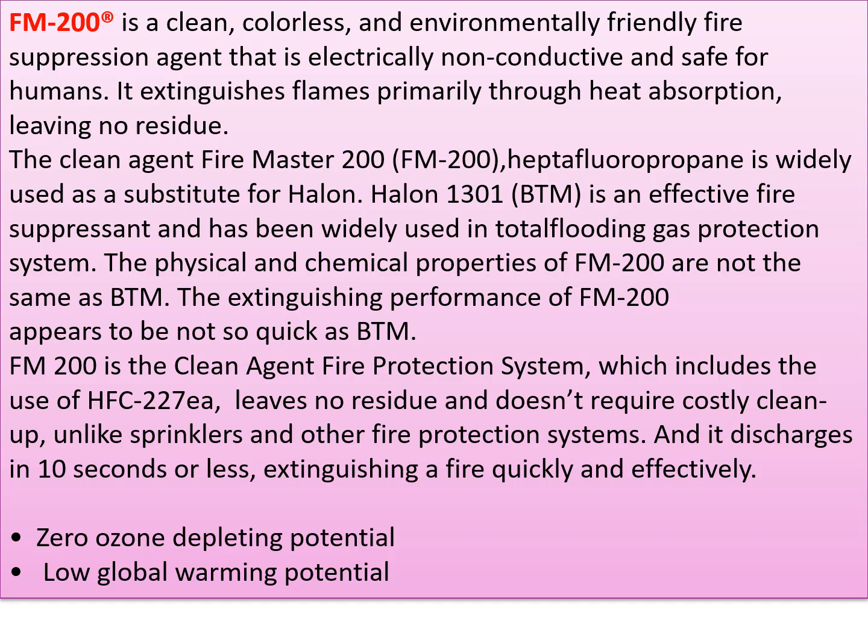It extinguishes flames primarily through heat absorption, leaving no residue. FM 200 is used widely because it has a zero ozone depleting potential and low global warming potential. These are the two indicators.